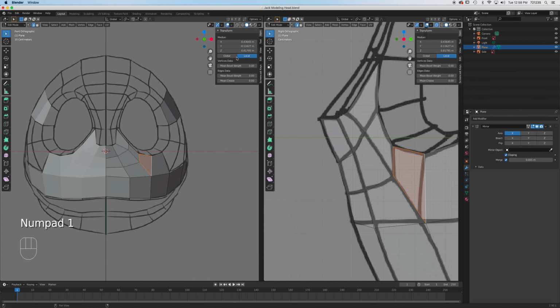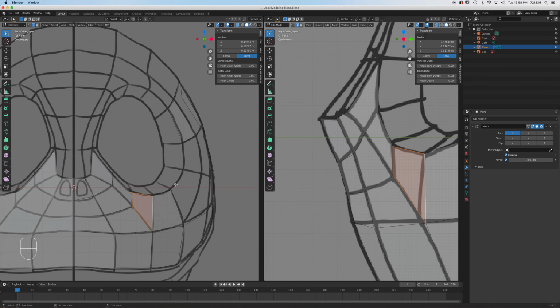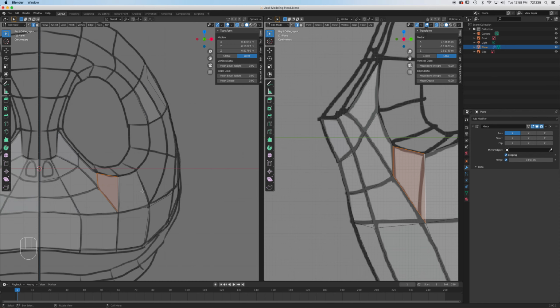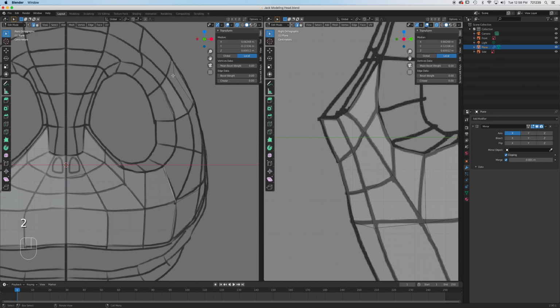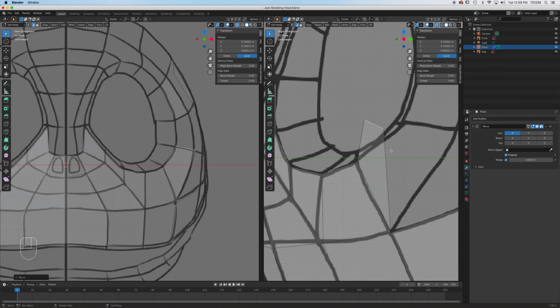All right, so it's coming along. All right, so now that's going to go up here. So we've got to create this line going all the way across over there. So I'm going to press E to extrude that, rotate it, and scale it. Once I have this position right here, let's match it here so that that's not too much of an issue. All right, once I have that, I can then extrude this. Oh, yeah, I forgot about this one. So I'm just going to press number 2, select both of those, and then press F.